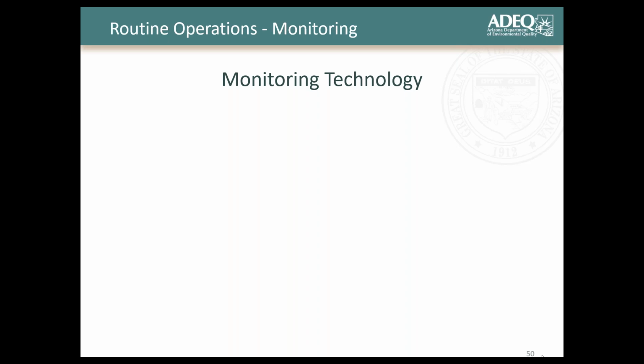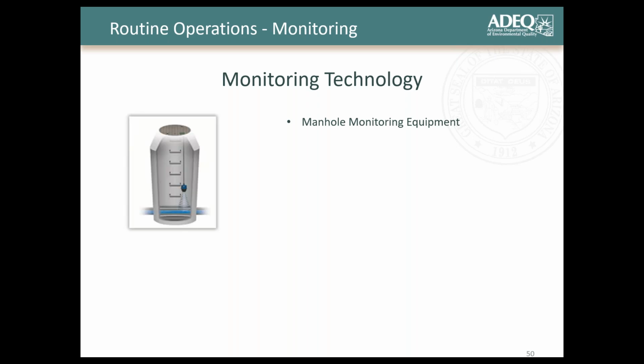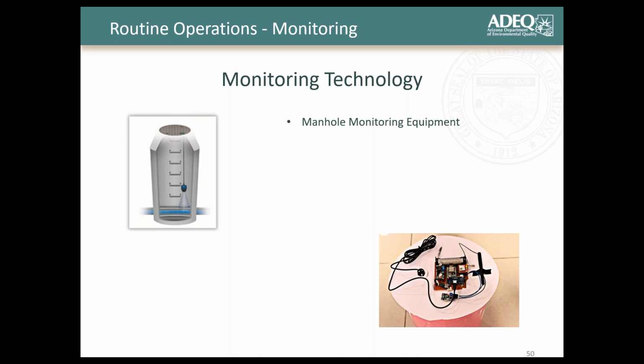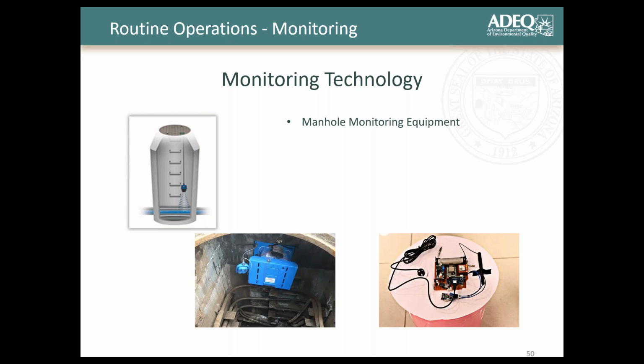I also wanted to give you guys some more tools for your toolbox. There's a lot of monitoring technology out there, especially manhole monitoring equipment, kind of newer technology, that gives you your own little SCADA system within a manhole structure. Here I give you a couple of different examples of manhole monitoring equipment. There are different brands and distributors out there for sure, so I tried to include as many as I knew.